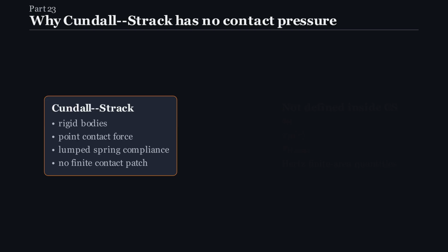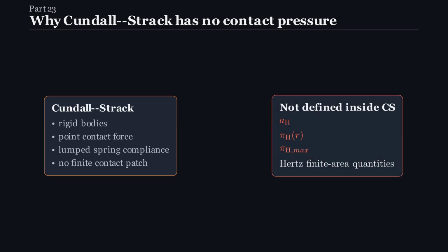Hertz contact has a finite contact radius and a pressure distribution. Cundall-Strack does not. It applies a point force between rigid particles with lumped compliance. Therefore a Hertz contact radius, local pressure field, and maximum pressure are not defined unless an extra artificial coarse graining area is introduced.